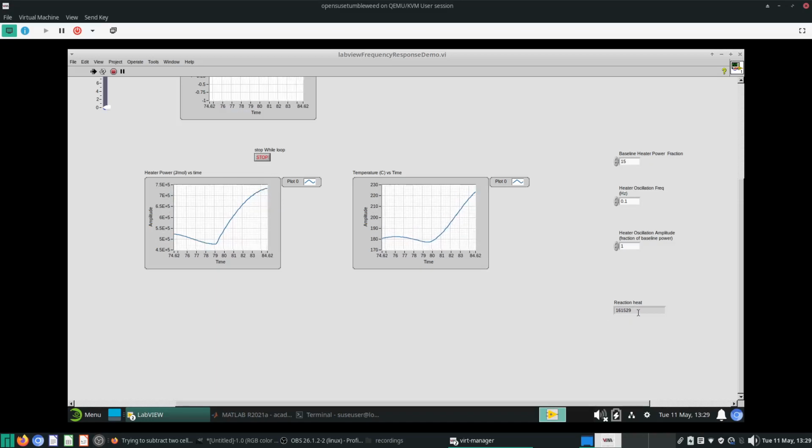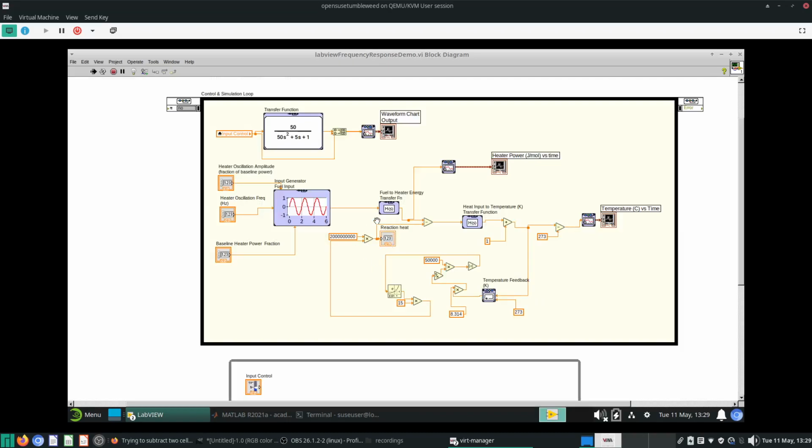It will go very high, but the thing is that even when you increase the temperature, the reaction heat isn't as high, because the temperature doesn't go up a lot, because the higher you go, the more heat will be consumed by this so-called endothermic reaction. So I have an endothermic reaction going on here. As you can see, I'm putting in a sine wave, and we go through the whole Arrhenius thing which I was talking about last time. Now we are pretty much set.